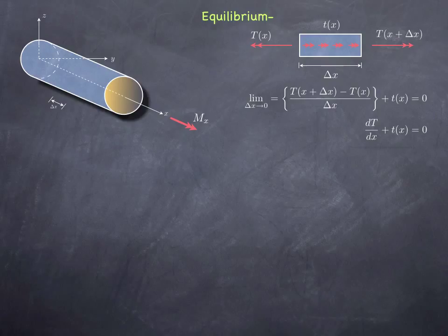of angular momentum about the x-axis, i.e. the moment equilibrium. If I do that, normalize that equation by delta x, and take the limit as delta x goes to 0, forgive the equal sign in that slide after the limit, that's a typo, then I will have obtained a differential equation that expresses the moment equilibrium about the x-axis: the first derivative of the internal torque plus the distributed torque is equal to 0 at all positions x along the length of